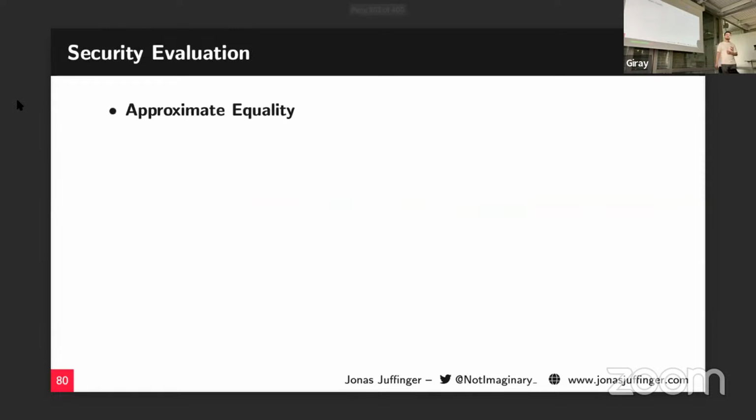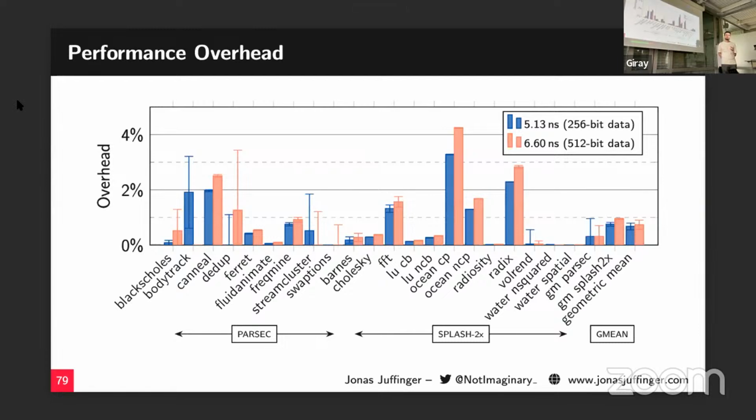We did a security evaluation. So it increased memory access latency, but it's not too bad actually, right? One can also choose to replicate some of these components in their architecture. Then you can read a chunk of memory, do the MAC computation over there, and at the same time access another memory location and start another MAC computation. So you can overlap those latencies, to provide more bandwidth.